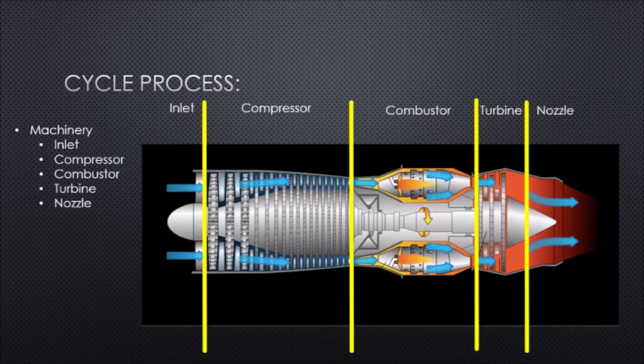flow down. Upon exiting the compressor, the flow will then enter the combustor, where air is mixed with fuel and then ignited. This raises the total temperature and pressure of the gas, which is then expelled over another set of blades called the turbine. The turbine extracts all of that energy and uses it to run the compressor. It transmits that energy through a shaft which lays in the middle of the engine. The hot gas is then expelled out the nozzle of the aircraft.